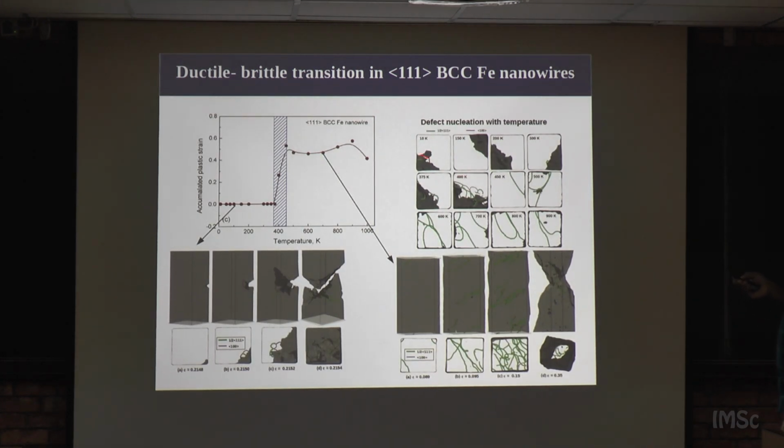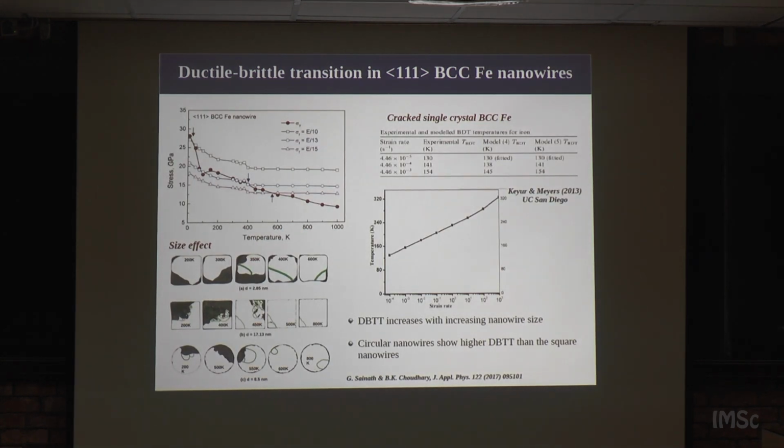This is even more clear: up to something around 400 K a crack nucleates with some minimal dislocation activity, while above this temperature there is no crack at all. The deformation is completely by dislocation movement. There is nothing inside the samples, only a crack nucleates and grows, and at high temperatures you can see that many dislocations activate and move in the crystals, and that leads to necking and then final failure in a ductile manner.